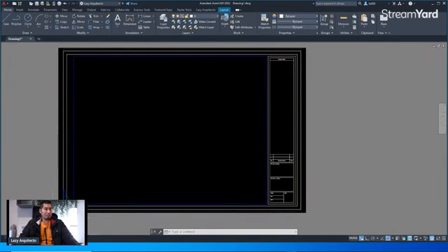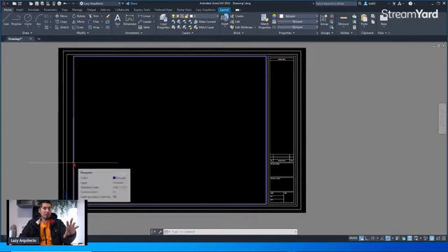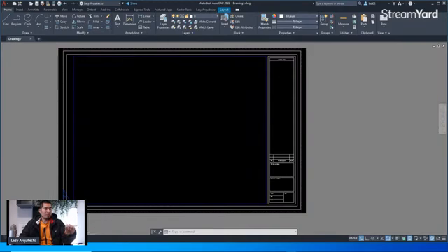And paper space is also called layout. So many people know this environment as layout or paper space. And again, you're gonna print your drawings here using how? Well, right now, let me show you. If I right click over here, let me expand this.